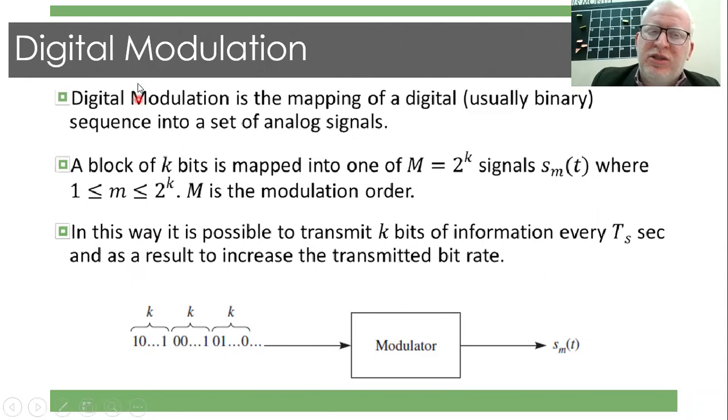This modulation turns digital whenever your message is digital. That's why in digital communication, you usually use what's called analog-to-digital converters in order to transfer your signal from an analog signal to a digital signal using three main steps, which are sampling, quantization, and encoding. After that, you will have a stream of binary data, which is a digital form of your message.